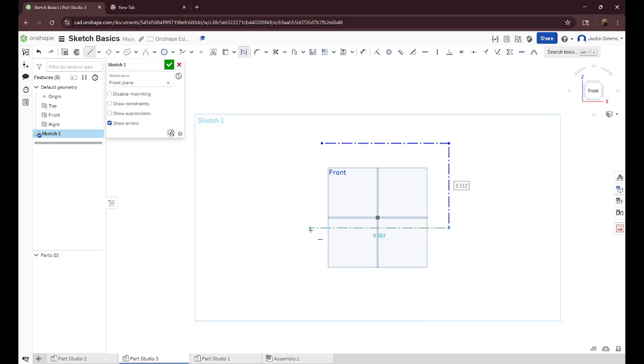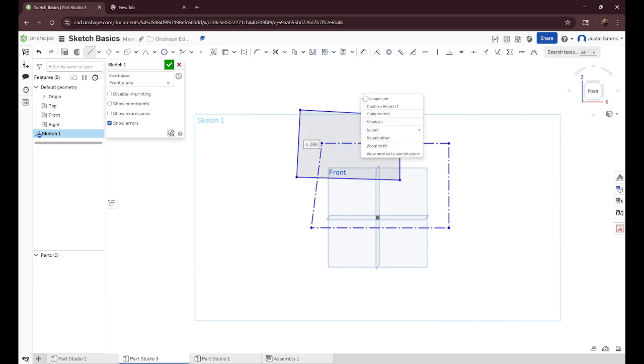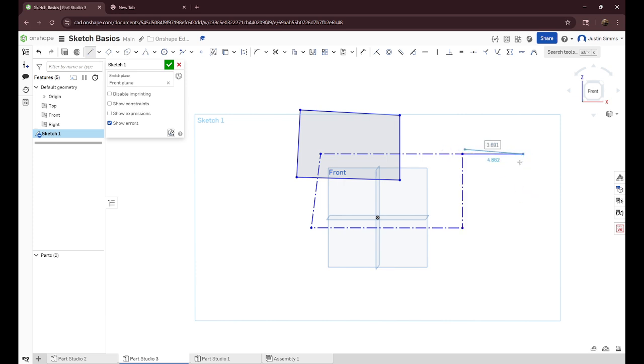As you can see, even when I make a closed shape, it doesn't fill in because the geometry is only meant for reference. If you're using this, it won't affect your solid lines, but you can use these points for your design. You can constrain off of them. They just don't affect the actual areas of shapes.